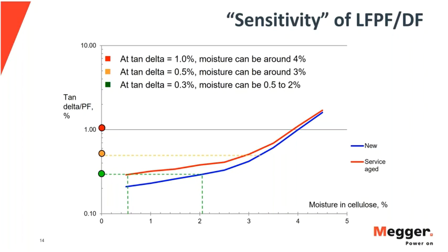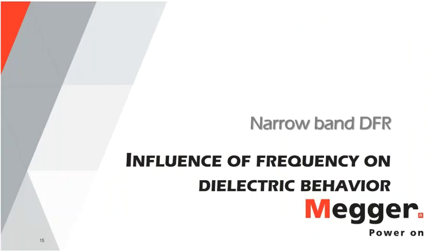So in summary, this lack of sensitivity to some problems at 60 hertz means that if you start to get some small changes in power factor, they could be significant. And that's why trending of power factor is the best analytic tool. But the challenge becomes filtering other variables that may be influencing your test results, for example temperature, so that the trending that you're reacting to is meaningful.